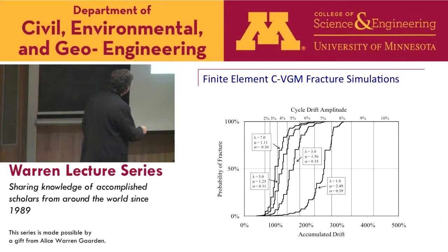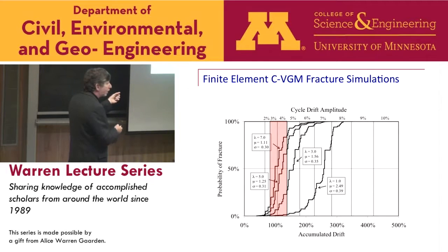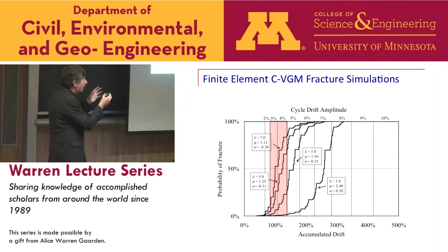If we're at a certain amount of accumulated drift, we'd have a certain probability of fracture in this location, that location, or the other. And we tended to find fracture in our specimen in this region here. Again, that fracture grew slowly there. So again, we can't, unfortunately, get a really precise, this is exactly how things correlate, because getting the properties of the heat affected zone is anything but a precise science, but a probabilistic estimate of the fracture.